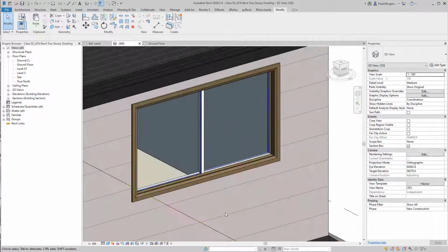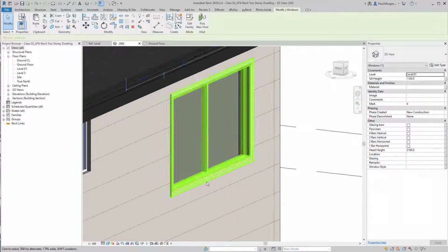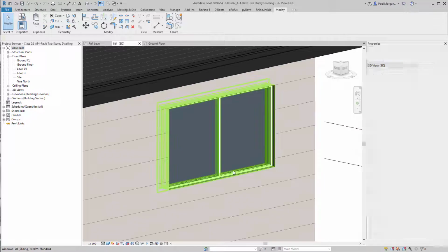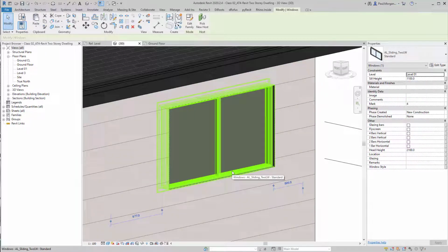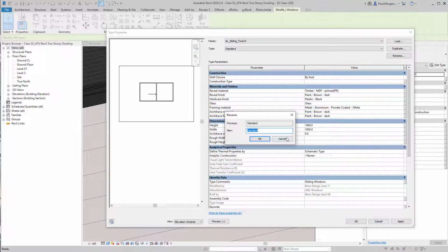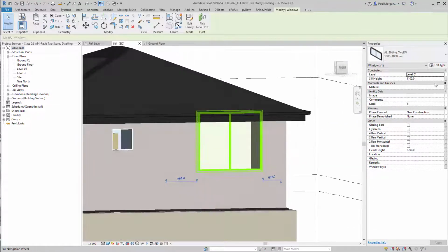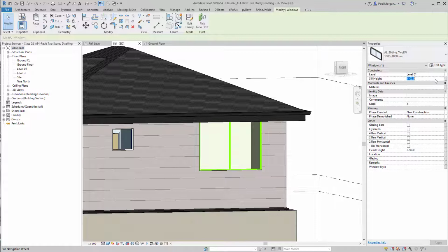So if you've got something like this, I flicked that around the wrong way. That architrave should be on the other side. So I just click on spacebar to flip that over like so. That's better. And the bedroom windows, what are they going to be? They are 16. Let's go edit type. What sizes are they given? Close. So the height will be 1600 and then 810 is fine. Or we might just change it to 1800 just to use round numbers. And I'll make sure I rename that so I can see that in the name. So 1600 by 1800. And say okay. That then updates. And that sill is going to be much lower.